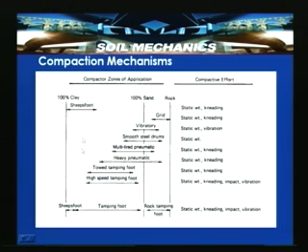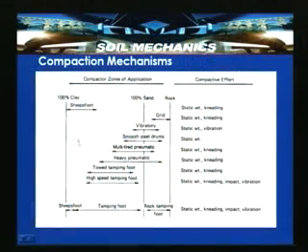The sheep's foot roller is used primarily for cohesive soils or fine grained soils having more fines, then the high speed tamping foot roller. As the soil transforms from 100% clay to 100% sand, you can see the variation in the type of compaction equipment used in the field: high speed tamping foot roller, towed tamping foot roller, heavy pneumatic roller, multi-tired pneumatic roller, smooth steel drum roller and vibratory rollers, and grid rollers basically for rocky strata.